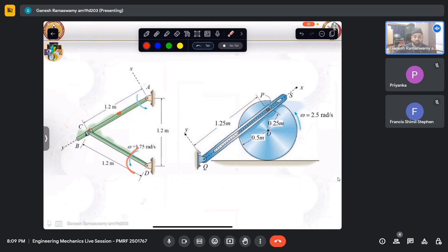So the crank is driving this. That is why this will resemble the slotted arm in this case. We can recast it as a different equation where this is a slot and this moves inside that. So whether it is over it or inside it, that doesn't matter. Which component is driving the other is what we should see, and then fix our rotating frame of reference appropriately.